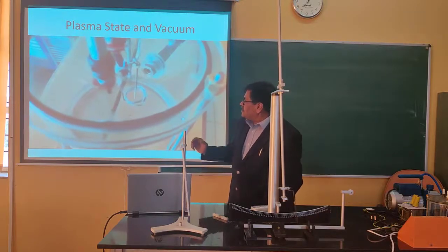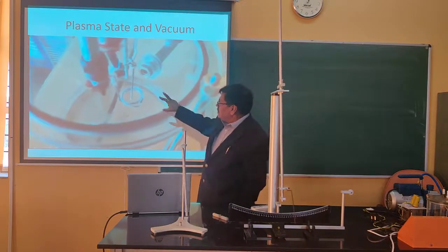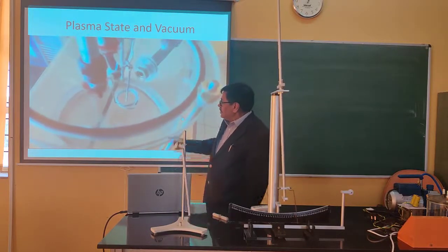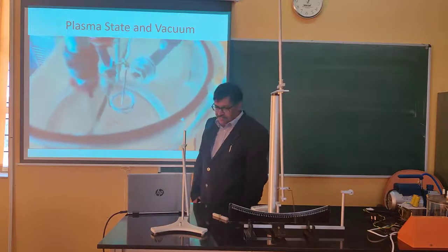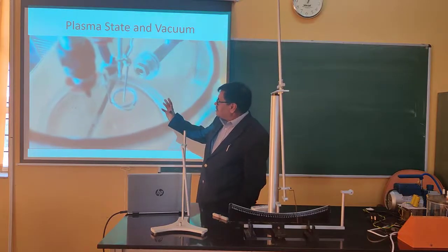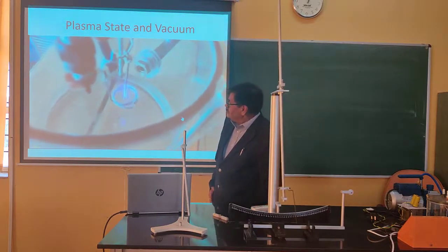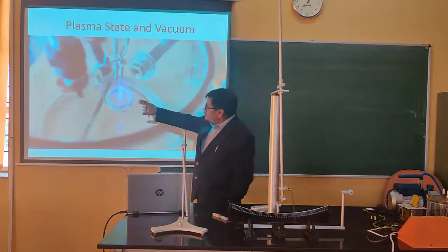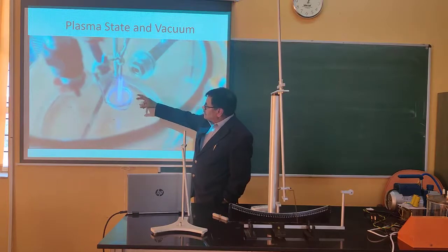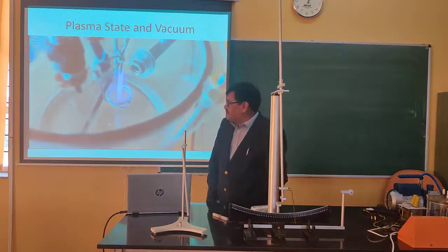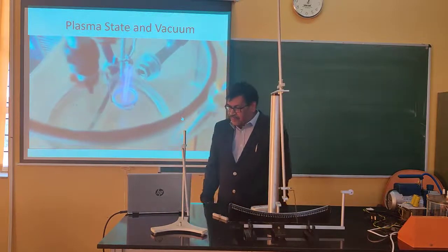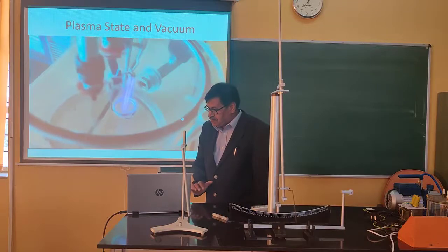As the pressure reduces, at around 700 volts, you see the gas discharge starts. And when there is a gas discharge, the positive ions drift to the negative electrode and the electrons are collected by the positive electrode, and you get a gas discharge, and that is how localized plasma can be generated in a small chamber.